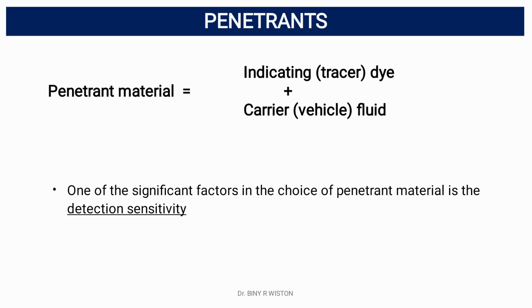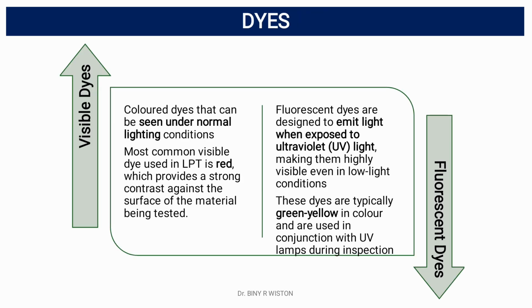One of the significant factors in choosing penetrant materials is detection sensitivity. Dyes used in liquid penetrant testing can be broadly classified into two main types, namely visible dyes and fluorescent dyes. Visible dyes are color dyes that can be seen under normal lighting conditions. The most common visible dye used in LPT is red, which provides a strong contrast against the surface of the material being tested.